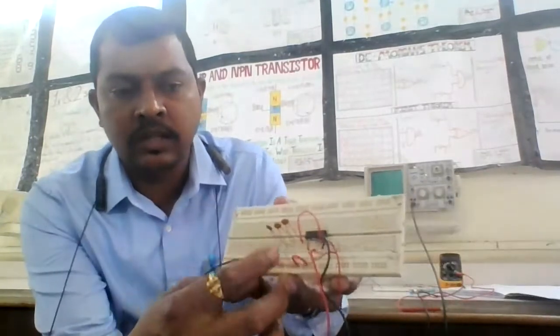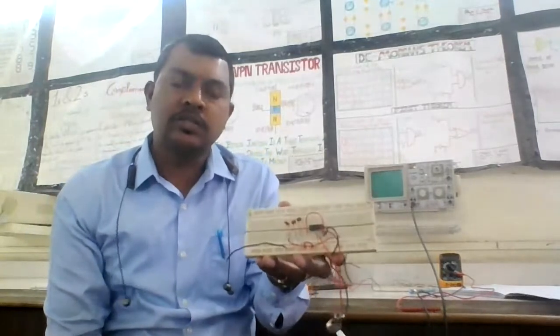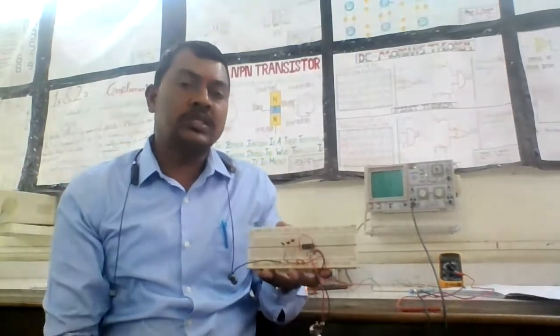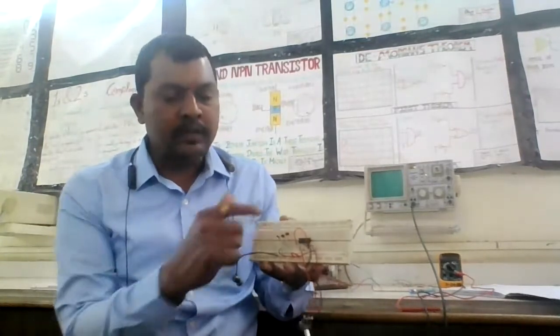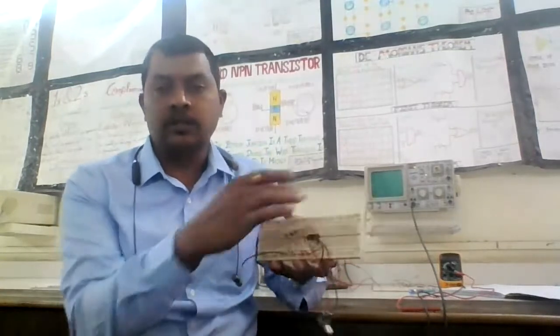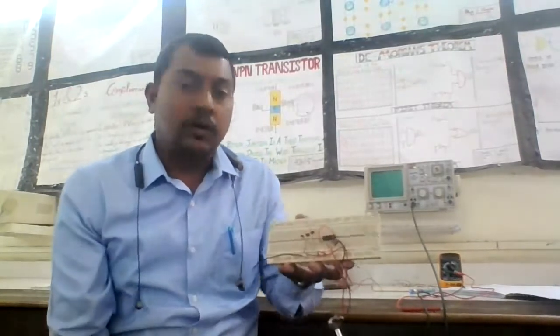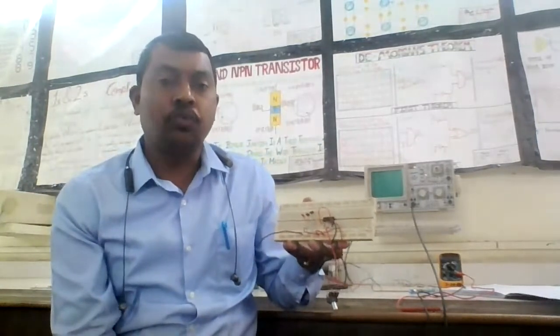These are the three resistances, and all three combinations of capacitor and resistance provide around 60 degrees of phase shift each, so the total is 180 degrees, and the rest of the 180-degree phase shift is provided by the other output of this op amp. We are using the TL084 op amp again, which has four op amps.